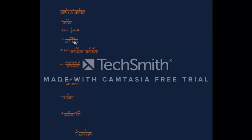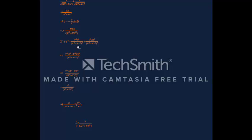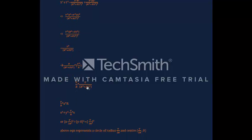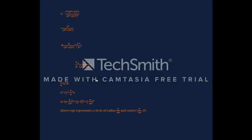which continues, and when we calculate, it turns out that x square plus y square is equal to V square R square upon R square plus XL square the whole square, plus V square XL square upon R square plus XL square the whole square. When you calculate, it comes out to be something like V by R into V upon R square plus XL square, which is nothing but V by R into V by R square, the whole square of reactance plus the whole square of resistance.